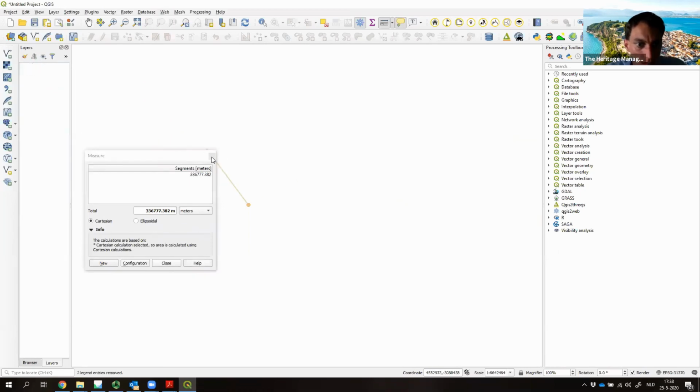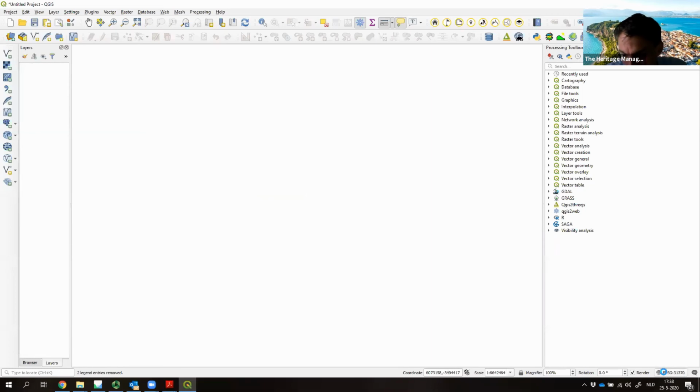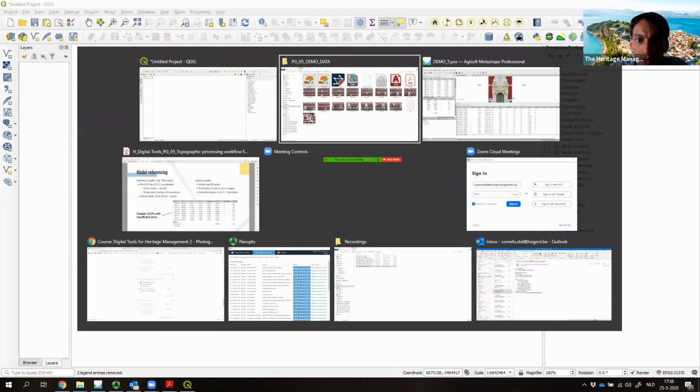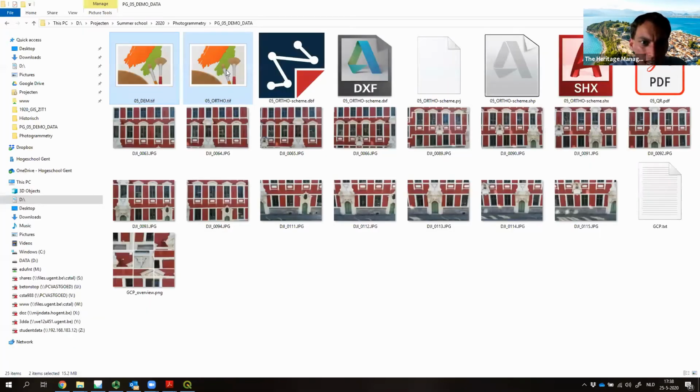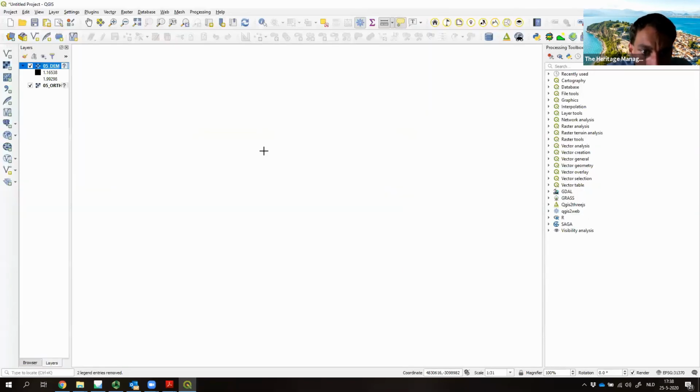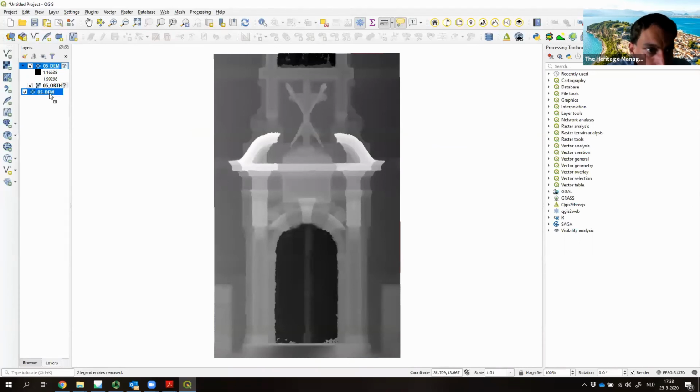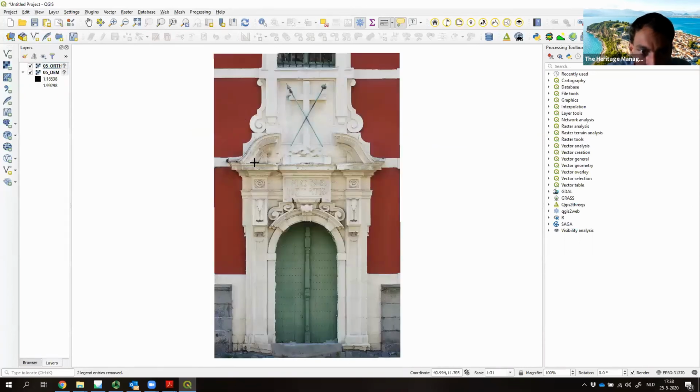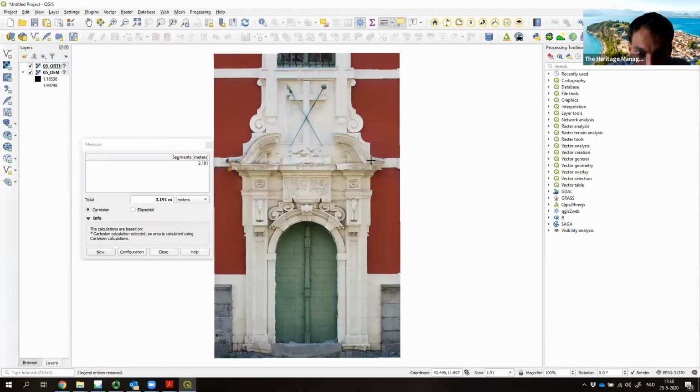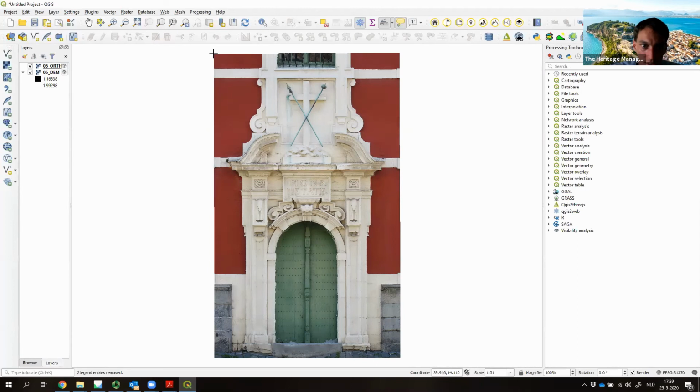So let me take these out. Take a Belgium coordinate system or any planimetric coordinate system, and then import the data again, and definitely not use WGS84 in that case. If I do the same now, I can get a value that is more reasonable. I have here the 3.3 meters. And also, I can measure the entire surface of my orthophoto.